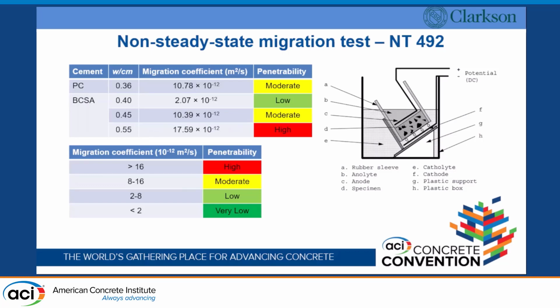We don't know if those rules should be applied to a different cement type, because we know that the chloride permeability problem really depends on several things, right? So it's not just about the pore connectivity and things like that. It's also about the pore solution.